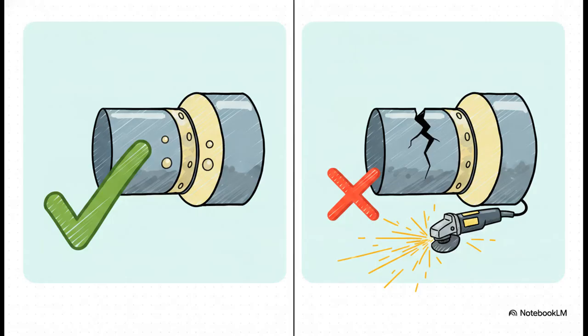Now, it's really fascinating how they draw a strict, uncompromising dividing line between what is just an allowable surface irregularity and what is a mandatory defect. An acceptable imperfection might be a tiny gas pocket or a minor slag inclusion. Those are just natural byproducts of welding. And as long as they fall within the strict dimensional limits detailed in the API tables, they don't compromise structural integrity.